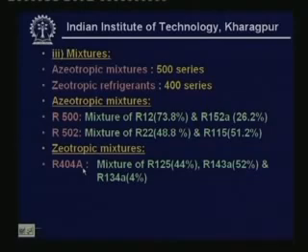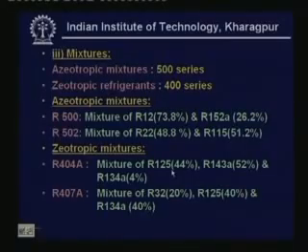To distinguish between isomers and others, small letters a, b, etc. indicate isomers, whereas a capital letter A means it is a mixture. Then again you can have R407A, a mixture of R32, R125 and R134a.